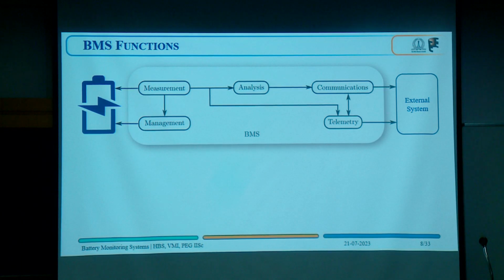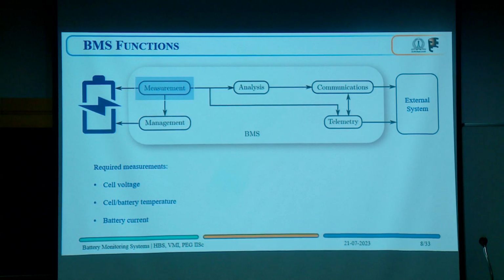So starting with the measurement. What are the basic measurements that we need to perform? That is basically cell voltage, battery or cell temperature, and the battery current.